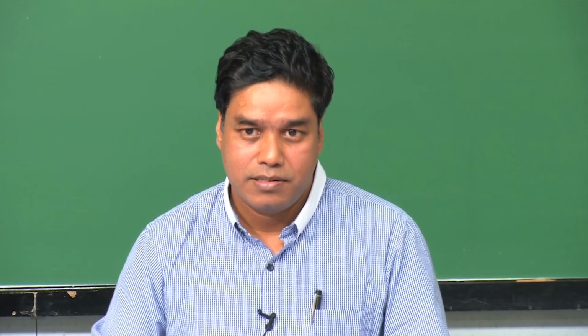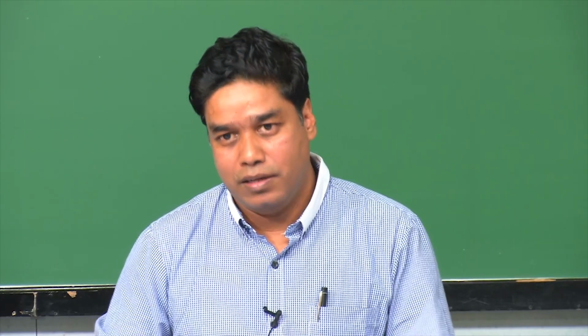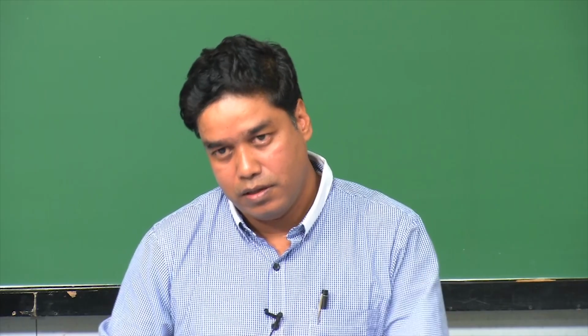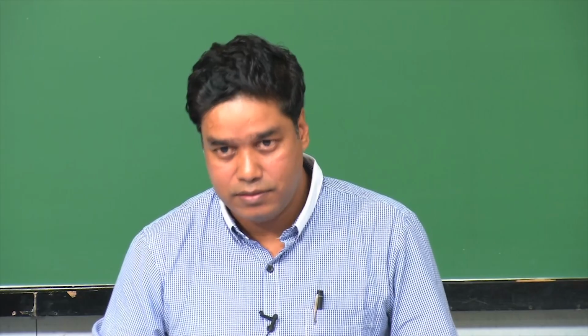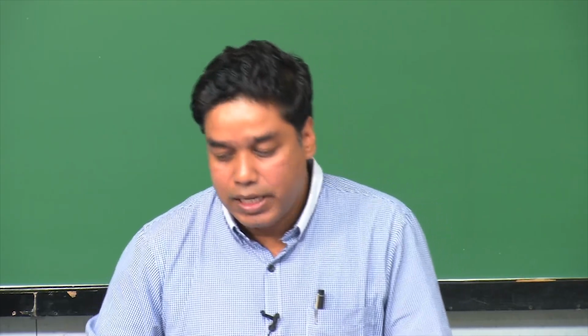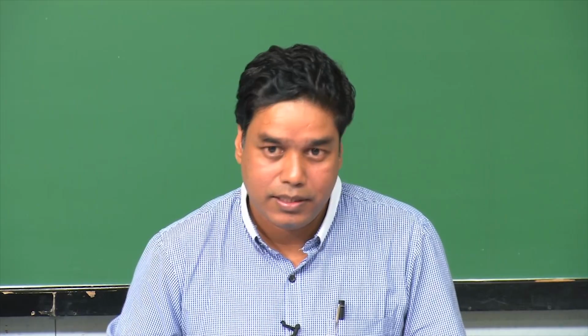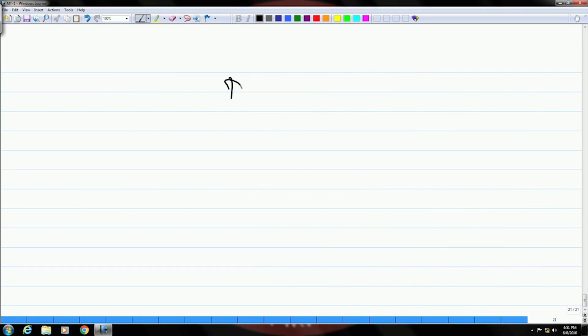So, if you want to inspect an as-cast surface, then it is recommended that you use dry particles, particularly when you know that the surface has roughness or a lot of undulations. Okay. So, in that kind of scenario, it is better to use dry particles rather than wet particles.